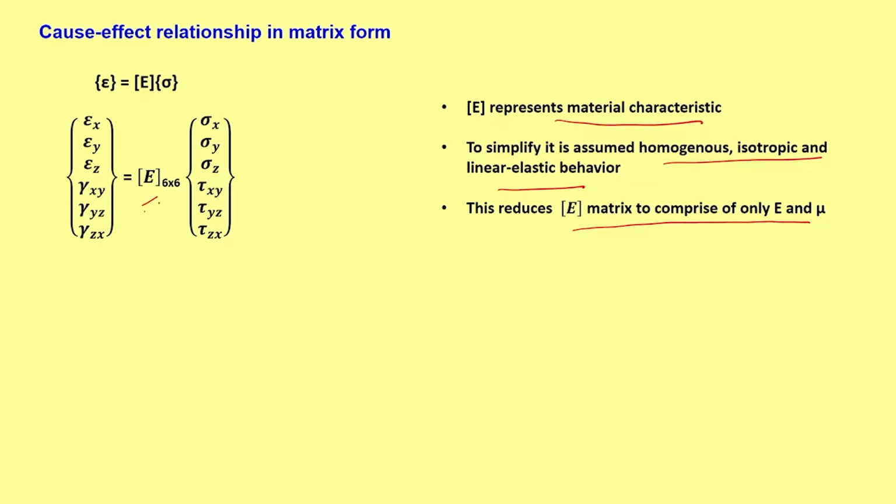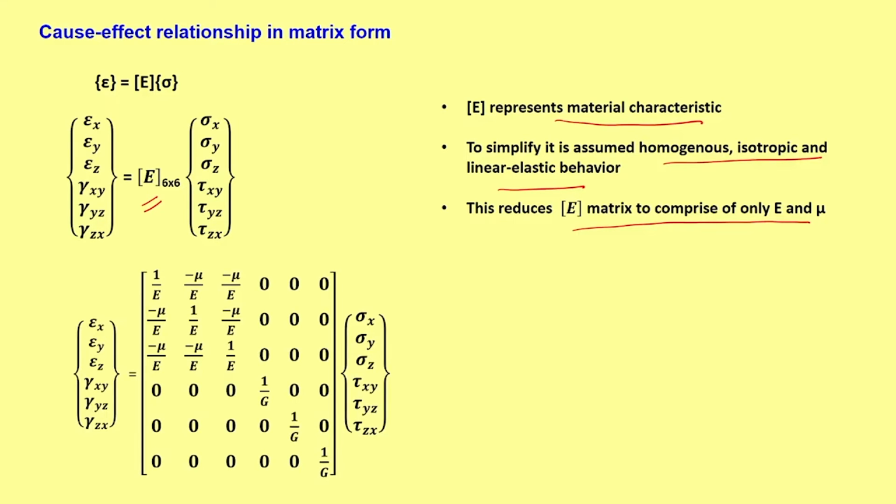matrix of material behavior. For linear elastic material, one can always obtain this, and this formulation of the matrix comes from the previous slide. We have the relationship, and that is rearranged in matrix form, that is all. So, this is a simple relationship wherein we talk about the linear elastic behavior, and that is why this particular model is so popular. If one can define the behavior of the material using linear elastic, then it considerably simplifies the problem and it becomes less computationally intensive.